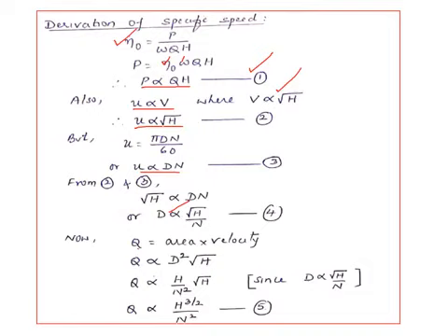This D can be used in the area. So we write an expression for discharge, which is area into velocity. In a Kaplan turbine, area is nothing but pi by 4 times D squared minus small d squared, where the hub diameter is also expressed in terms of the outer diameter as 0.35 capital D, something like that. So ultimately it will be in terms of D squared. So area is proportional to D squared.